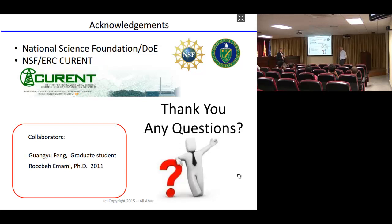On the other hand, if you consider, at least for the time being, the infrastructure supporting SCADA, I don't know about relaying, but SCADA versus the infrastructure supporting the phasor measurements, they are not the same. So in other words, there may be situations where a storm comes through and you lose SCADA, but you may not lose PMU connectivity. So in that case, this may be just a complementary solution. If they're using different channels, yeah.